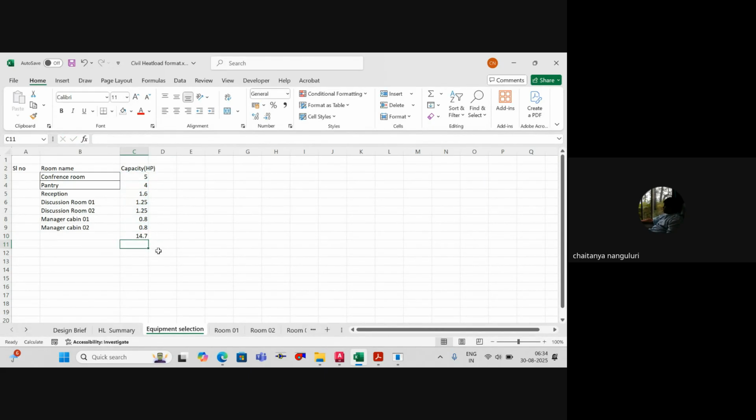So in this, as a general thumb rule, we'll go for at least 20% diversity for safety reasons. You can go for more, but not every OEM will provide it, and you'll have compressor issues depending on your application. You can even go up to 50% diversity, but for office applications, for safety reasons, we generally consider 20% as the diversity.